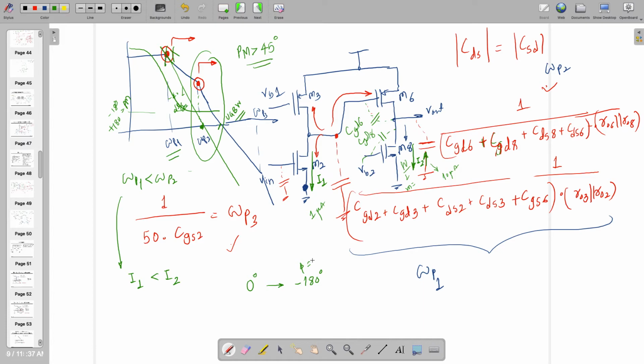So if you want to stabilize it, you have to take the second pole outside. For that you need to increase this current, without touching anything else. So that's the standard way. Sometimes some people touch I2 as well as I1, but there is no point in that. One at a time only, not both. So the best practice is to fix I1 and then go to I2.